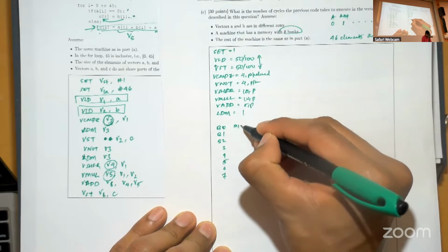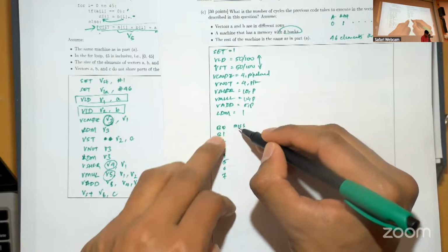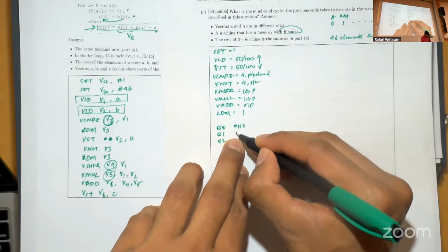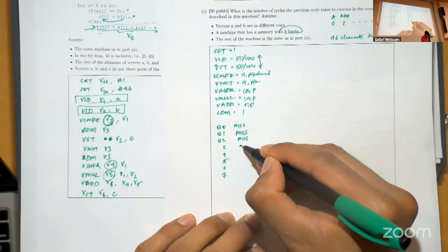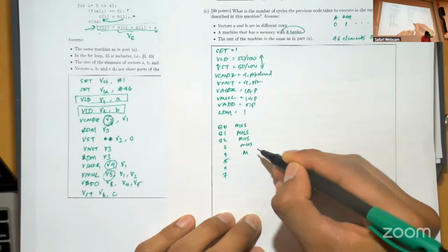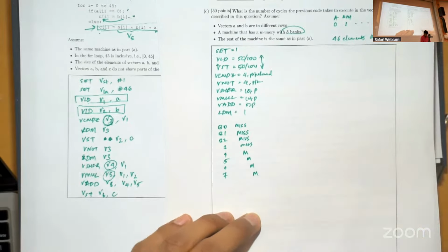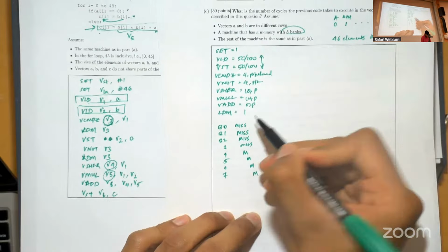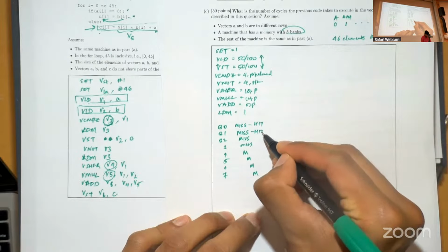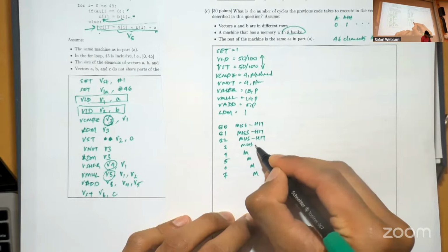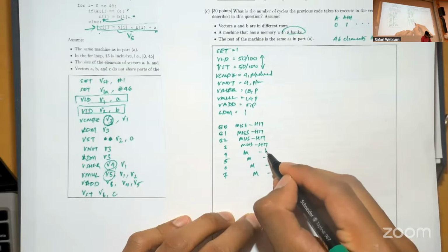The first access is always going to be a miss because everything is pre-charged. So you have a miss. And then after one cycle, you can issue another request to B1. That's also going to be a miss. You keep following this with misses, and I'm going to shorten this and write this as M. After the miss in the first one, you'd have a hit because the row is already open, right? And this follows here as well.